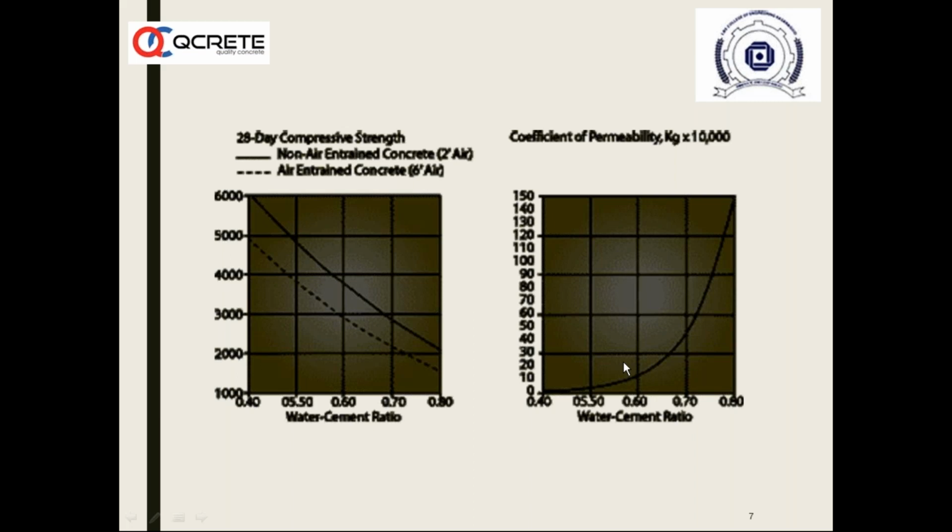The biggest enemy for reinforced concrete structures is water and oxygen. When water and oxygen get into the RCC and touch the reinforcement bar, corrosion takes place. For example, you have a 1 mm thickness steel bar. The corrosion product will swell up to 4 to 6 times.